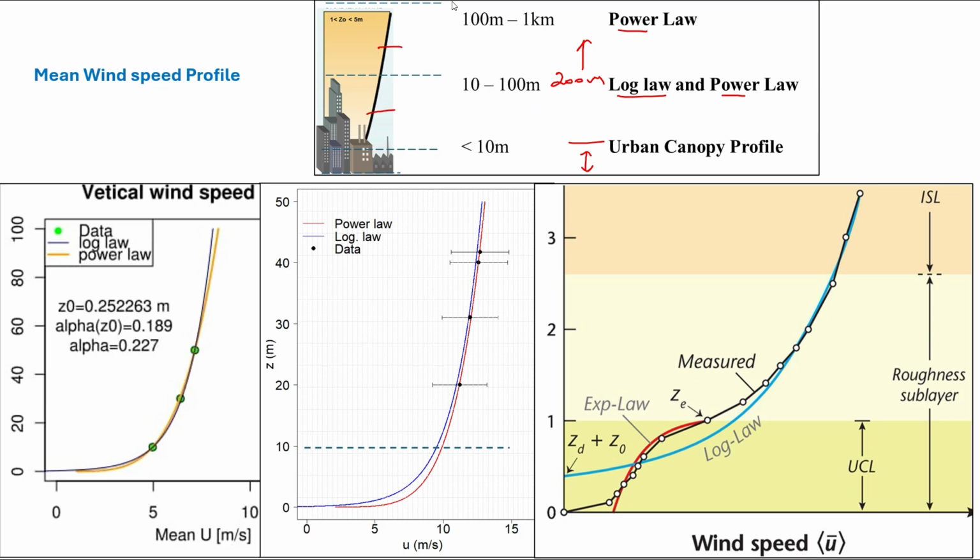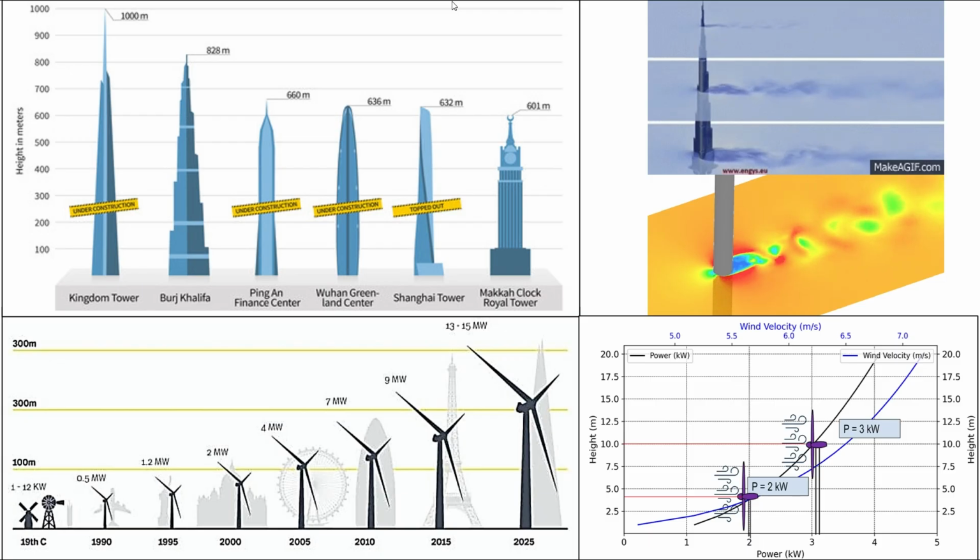And where we use these formulas in industrial aerodynamics applications is mainly in building aerodynamics and wind engineering. So if you take a high-rise building or skyscraper, for example, if you consider flow over a bluff body, then at a particular Reynolds number, that is at a critical Reynolds number, there will be alternate vortex shedding.